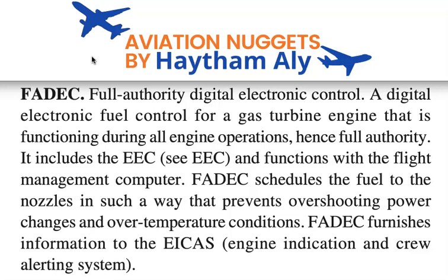If I speak with any pilot or any aircraft maintenance personnel about the FADEC system, probably I will hear that the FADEC is the EEC or Electronic Control Unit. I need to tell you that FADEC is not only the EEC, the Electronic Control Unit. FADEC is the EEC plus engine systems and engine sensors that we call peripherals. FADEC equals EEC, yes, the computer, plus engine systems and engine sensors.